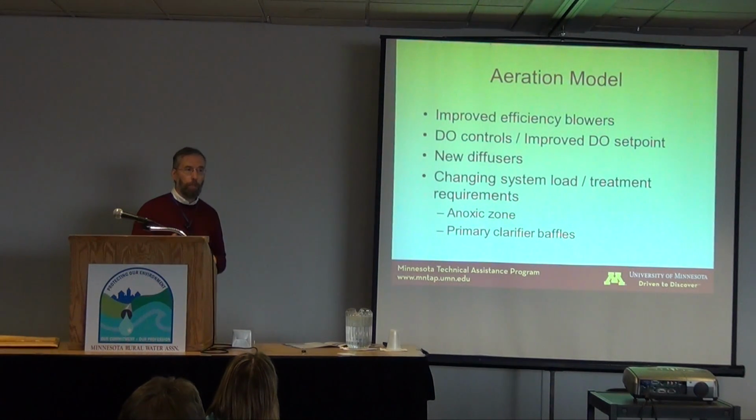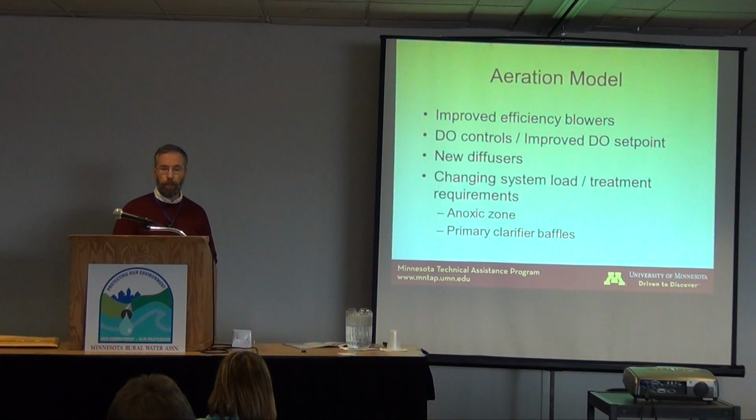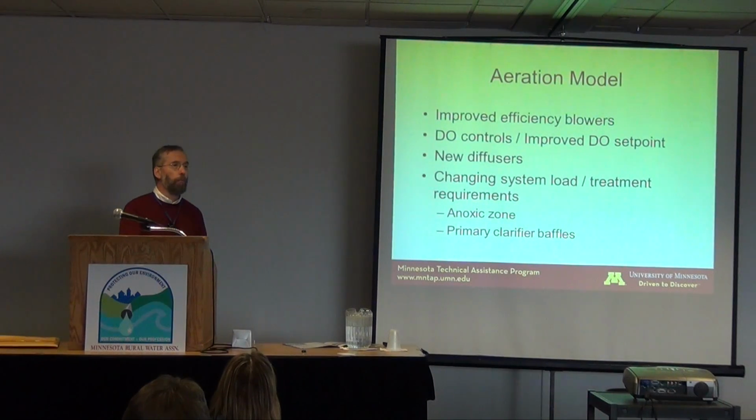And the model can be used for changes like improved higher efficiency blowers, more appropriately sized blowers. It works well with looking at adding dissolved oxygen control or improved set points. It can be used to evaluate different diffusers or changes in system load or treatment requirements, including adding anoxic zones or improving primary clarification or settling with primary clarifiers.